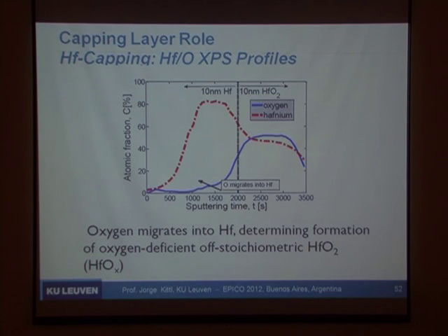So in our systems, one of the important things is that we have a vacuum cap. Why? You don't need it, you can switch without the cap, but the vacuum cap definitely creates a region next to it with a large number of vacancies. That helps the process of forming filaments without creating too much damage, so you can switch them better later, etc. And you can see by XPS that indeed you have oxygen vacancies close to the hafnium. So it's a non-stoichiometric layer in between.